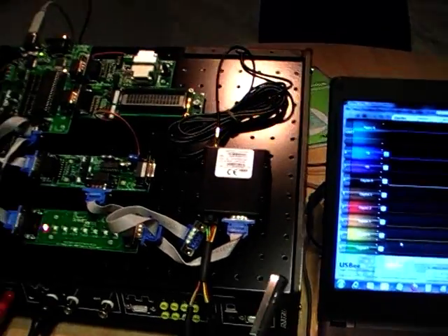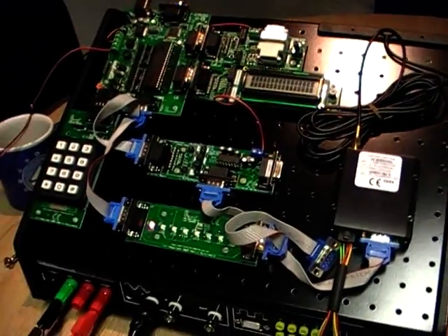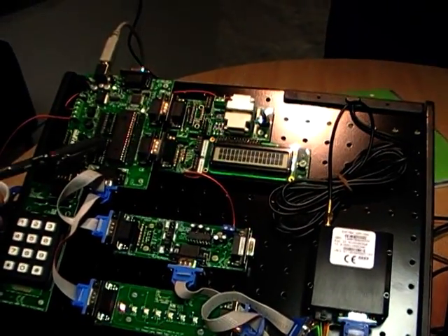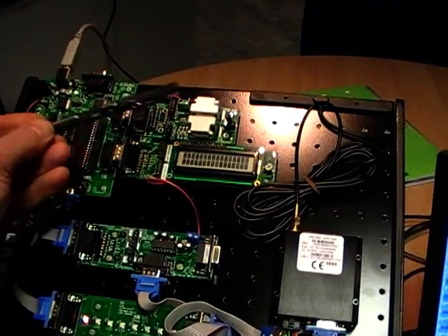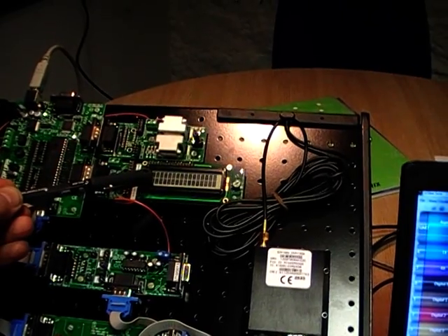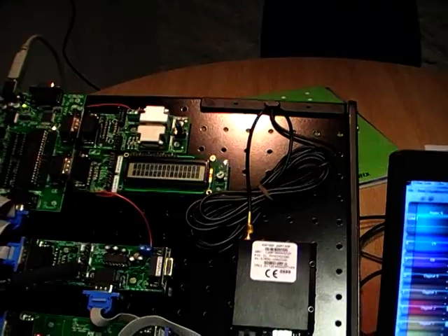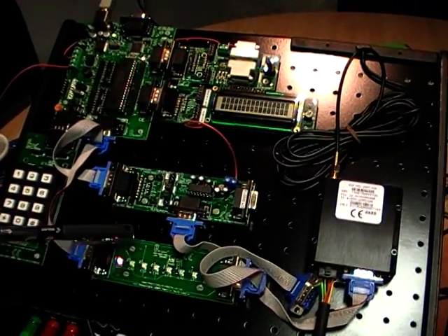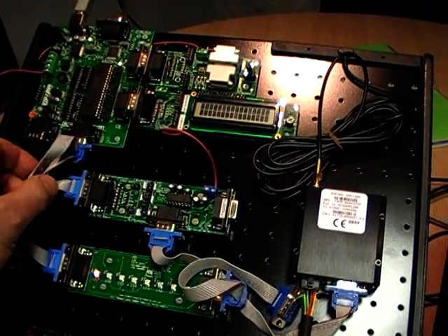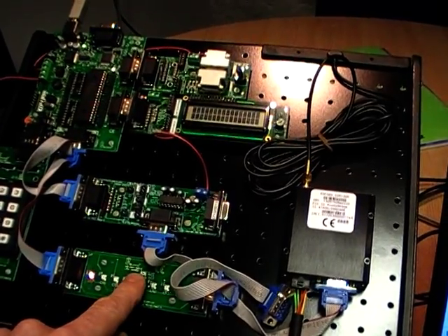On the top of the workstation I've got some E-blocks, a PIC micro multiprogrammer. On port A I've got a sensors board, on port B I've got an LCD board, port C, which is the comms port, I've got an RS-232 interface, and that's paralleled up with just an LED board.